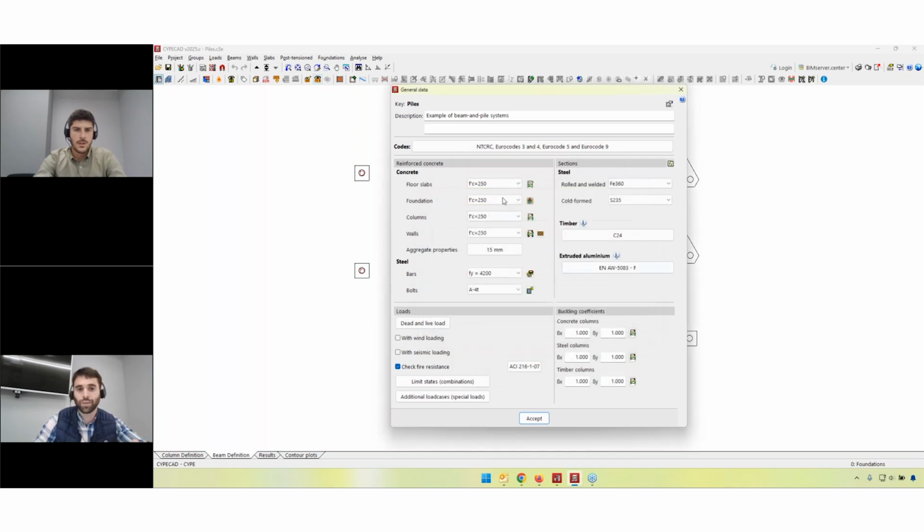For now, let's go. Adriano, sorry, yes. One fast question. I know that it can be applied to a lot of codes because it's generic. The engineers should introduce these safety factors, but the factors that we give by default, I think these factors are on the side of the safety, right? Always. Exactly. In case it is not defined by the user, the safety factor will be defined as 3. So the applied loads divided by the resisting loads is 1/3, or in reverse 3. So yes, Cype always decides on the safety of the structures. So this would be no problem, even if the user doesn't define it correctly.